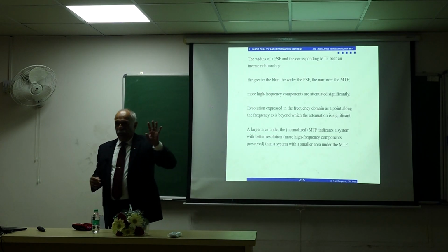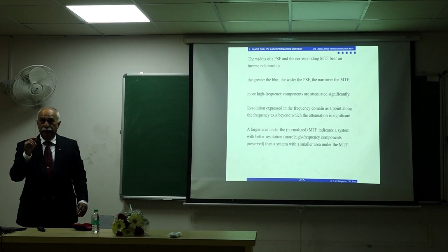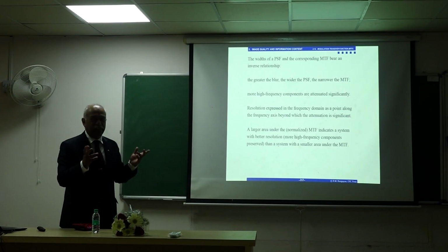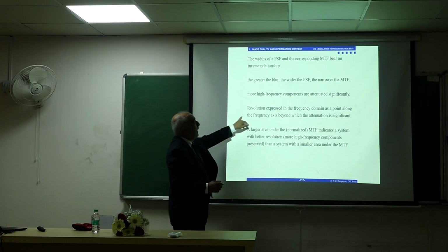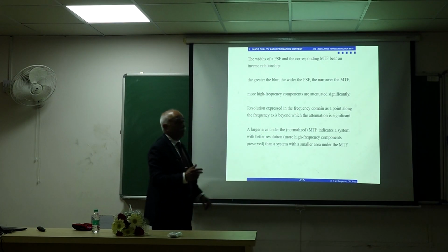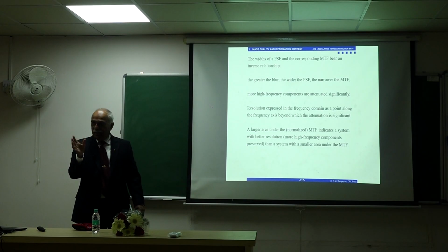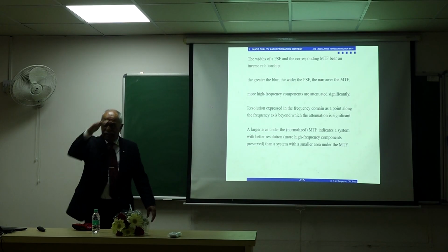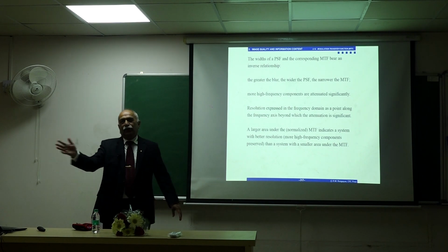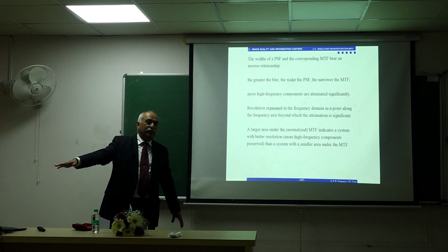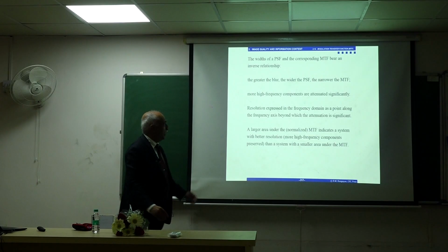Resolution, I mentioned a few definitions of resolution. You can also define that in the frequency domain. Some of us, especially in electrical engineering, like to work in the frequency domain. It is a point along the frequency axis beyond which the attenuation is substantial, significant. How do you define significant, substantial? You have to set some rule, 10% of the maximum something, and say, that is my resolution. Beyond that, it's too much loss of frequency components. They're being suppressed too much.